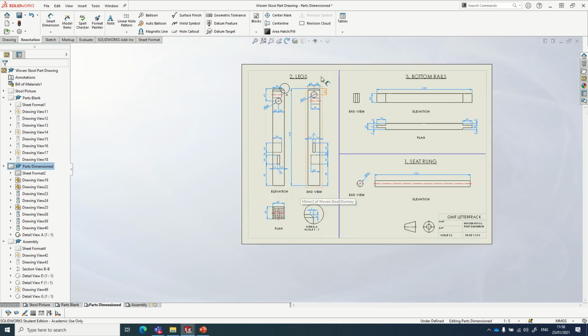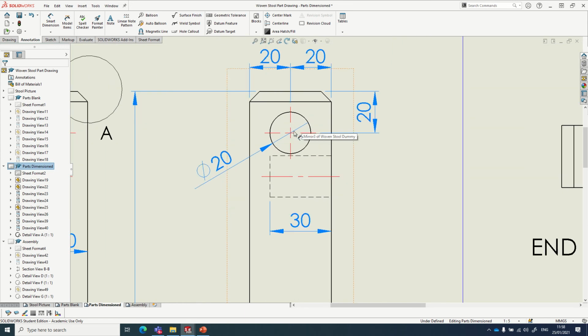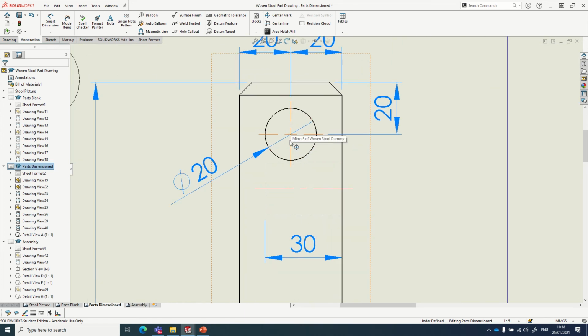It's something that I find students tend to forget about, the center lines, because it's not an edge that you see. They tend to leave them out, but just make sure you don't do that. So center marks and all our standards apply. Our center line is long dash, short dash, and extends out past the piece. You can see the feature stops here, so it just extends past that. It's far enough away from this edge that we wouldn't continue it out to the very edge. Same with our center mark, continuing out past the edge there, like so.